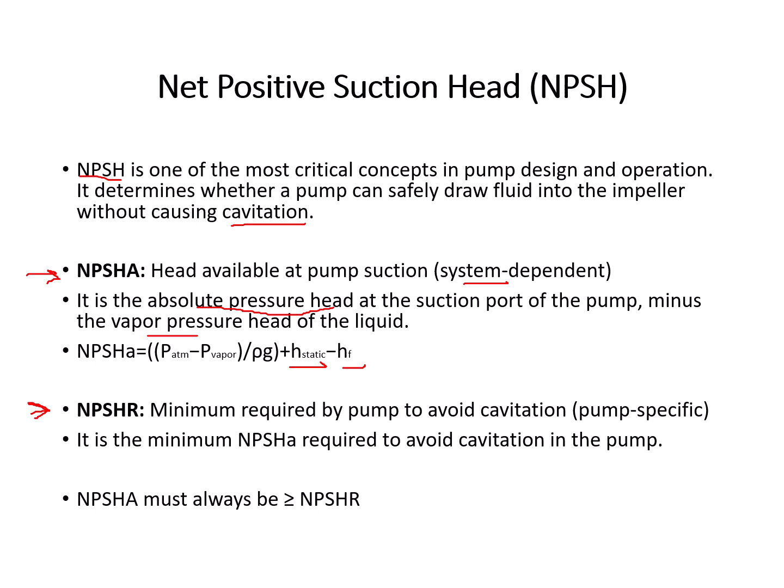Net positive suction head required is the minimum required by the pump to avoid cavitation. It is pump specific. The pump requires this net positive suction head to avoid cavitation. It is the manufacturer data that will show you, for each pump, the net positive suction head required.